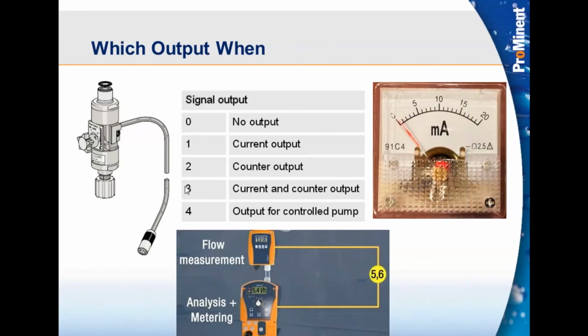It's just intended to go to the customer. Whether they want it for a remote display, out to a chart recorder, whatever they're using that 4 to 20 signal for, that is a powered loop going out. And I believe it can drive up to, I think I saw 400 ohms. If that's a question, how much can it drive? We want to verify that. I'm thinking that I saw it was 400 ohms, but